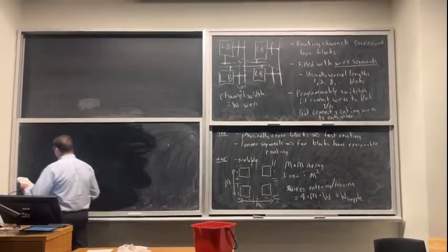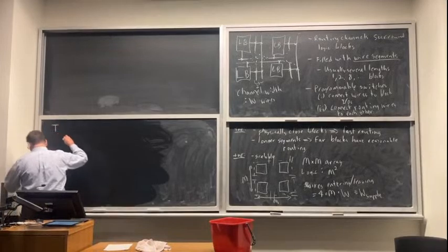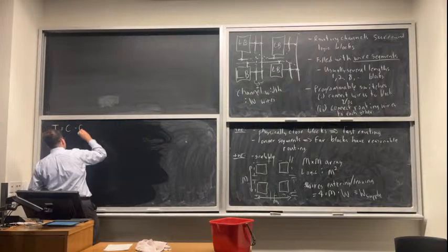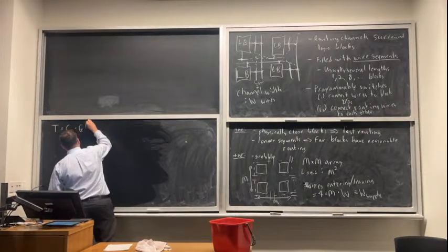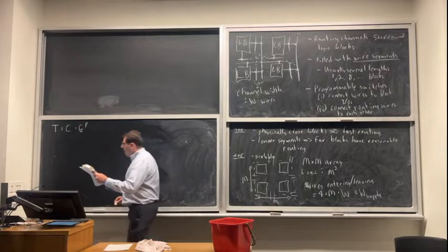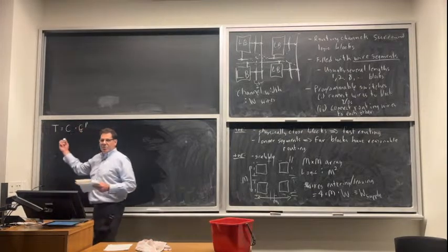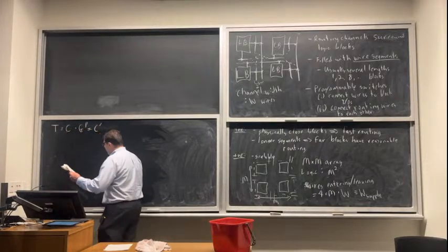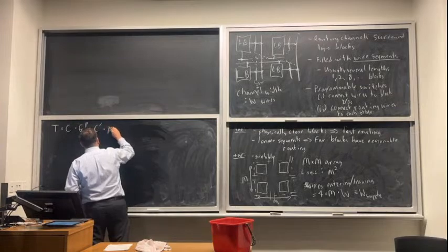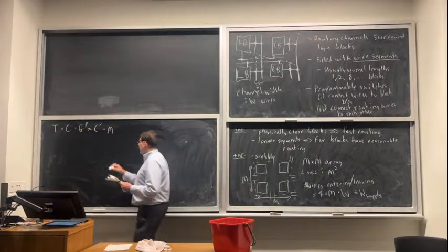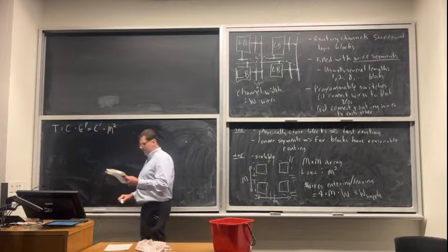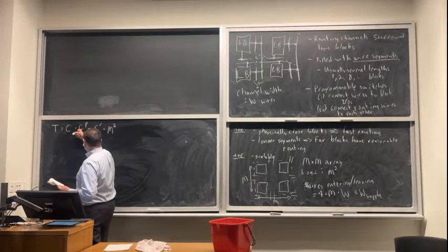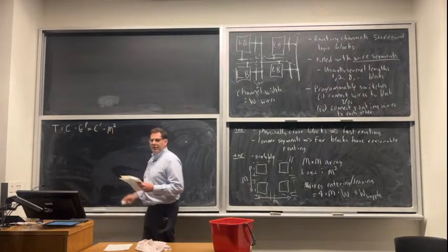Now I'm going to go to Rent's rule. Rent's rule says the number of terminals is equal to some constant times the number of gates in my logic, raised to the Rent exponent. I'm not going to work in gates, I'm going to work in logic blocks, so I'll rewrite this as some other constant times my number of logic blocks, which is M squared, all taken to the P. I've just replaced G to get this new constant and M squared.